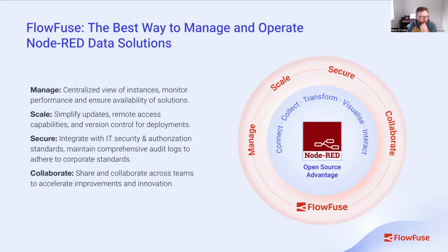It's true to say Wago have developed some of your own nodes for interaction with your hardware, haven't they? Yeah, we have one for the power measurement module. That's a really common one. You basically just drop that node in and point it to the index for that module in the rack, and it will provide the voltage and current readings for you. Nice.